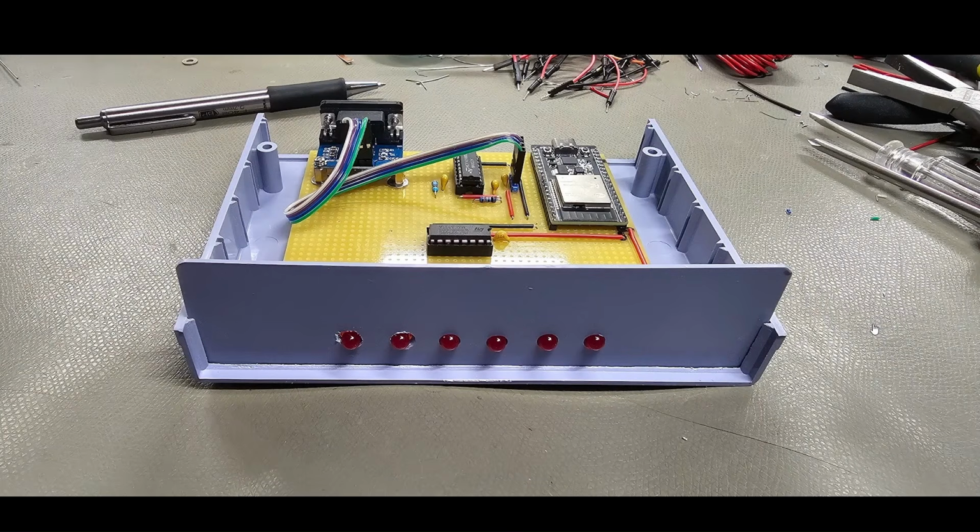So here's the board mounted in the case. When I was cutting the holes for the LED, I didn't have the plastic secured to the drill press, and so twice my drill got away from me and cut the hole a little weird. But the rest of them turned out good. So that was just a learning experience for me: even if it's plastic, you do need to clamp it down so it stays put. Otherwise, you're going to get elongated holes like I did.